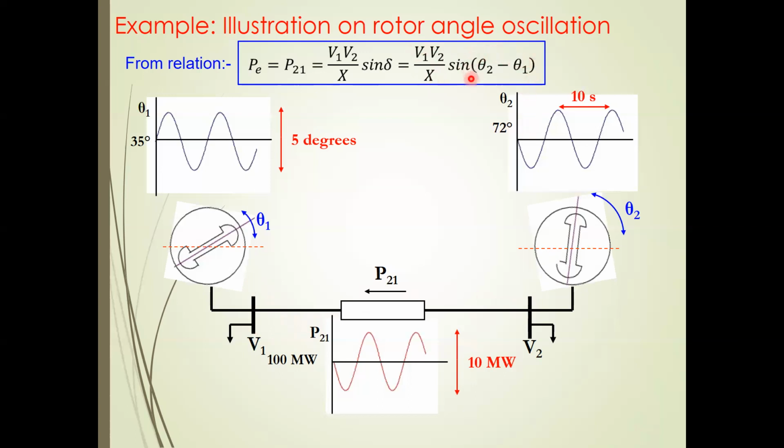And thus the amount of power flow, for a given voltage and the reactance of the line, is altogether dependent upon the angle difference between the two generators. If you want more power flow, then obviously the angle has to change, the angle has to be more. We do that by governor setting. We will have more power flow, but again, what could be the maximum angle difference? Yeah, 90 degrees. Okay, 90 degrees is okay.